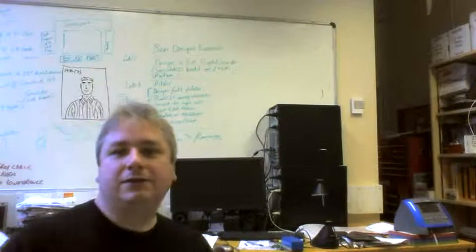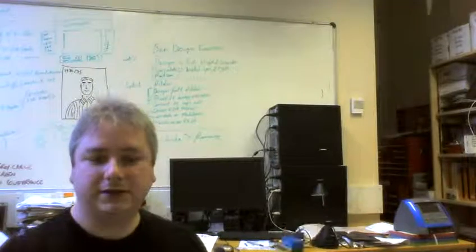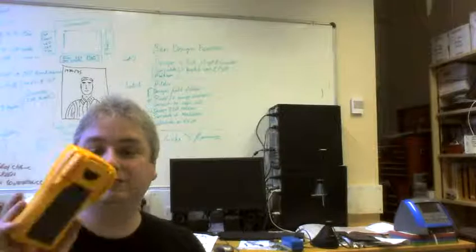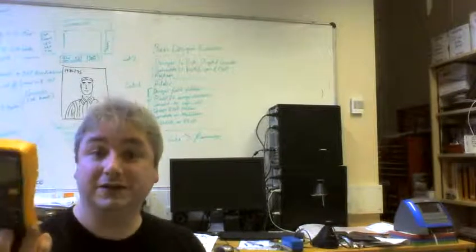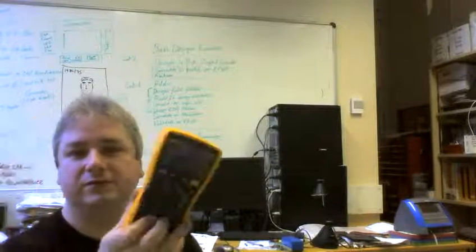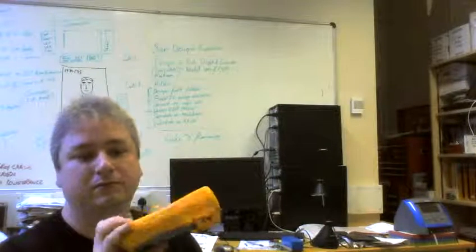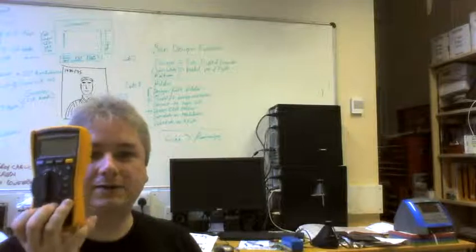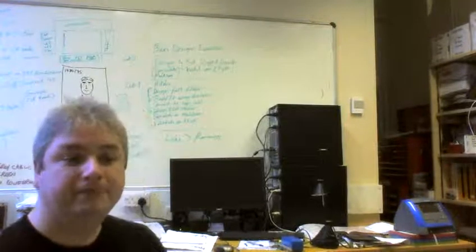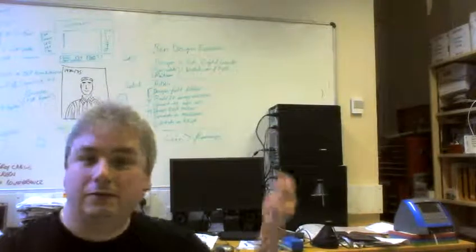Anyway, that's AC on multimeters. I've been concentrating on volts. Exactly the same problem applies when you're doing current as well, except you use the meter in series, just like when you're measuring DC current. For AC currents, it's still got exactly the same frequency range.